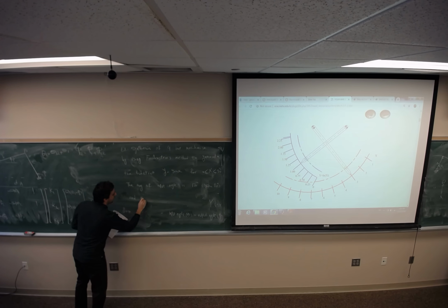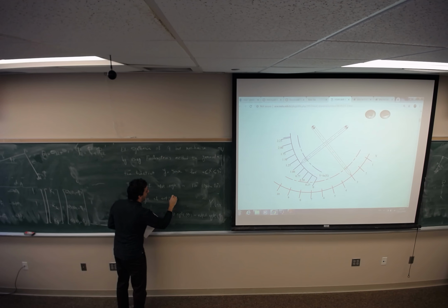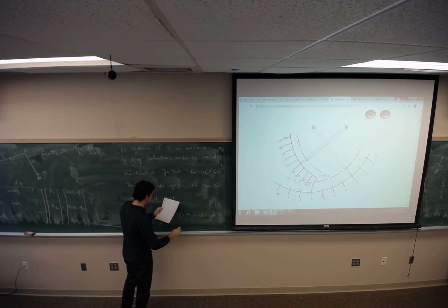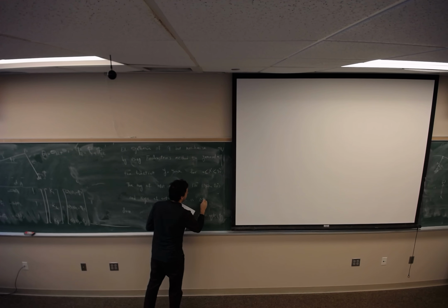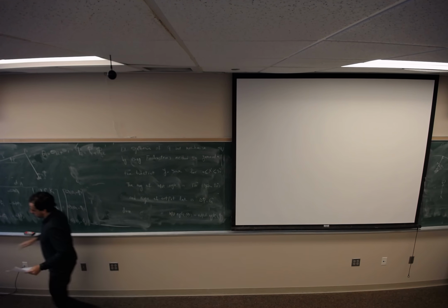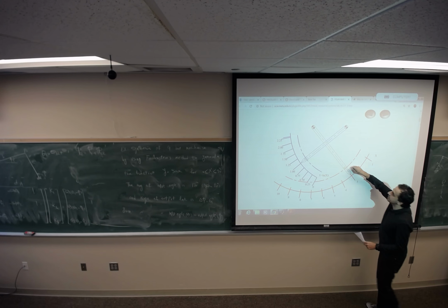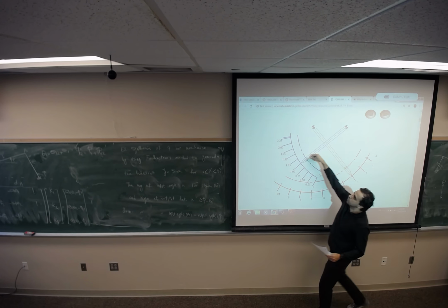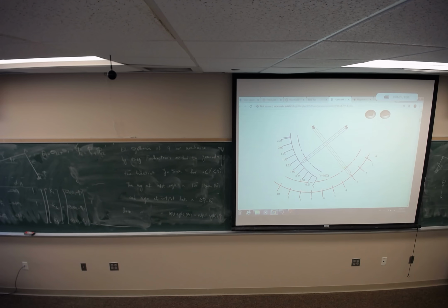And the range of the output link, the phi, we would like to have 60. So when the input link is rotating by 120 degrees, we would like the output link to cover just 60 degrees.